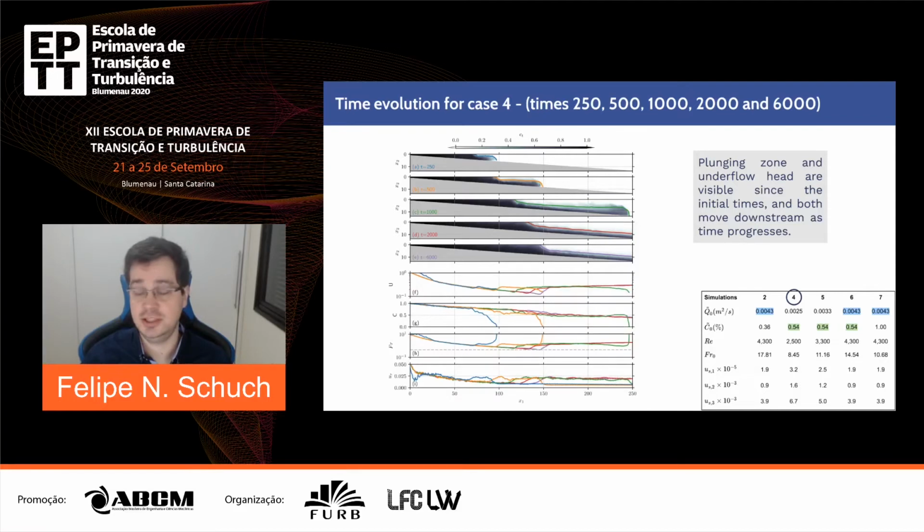And then the depth average quantities. Velocity is the inverse of the channel's depth, so that is the case upstream of plunging because channel depth is increasing. At the plunge point we see the collapse and acceleration of the flow, and the velocity is near constant in the submerged dense current. The depth average concentration decays due to sedimentation.